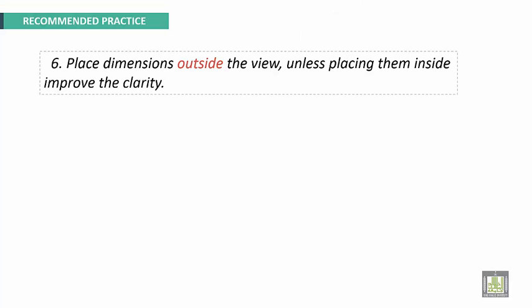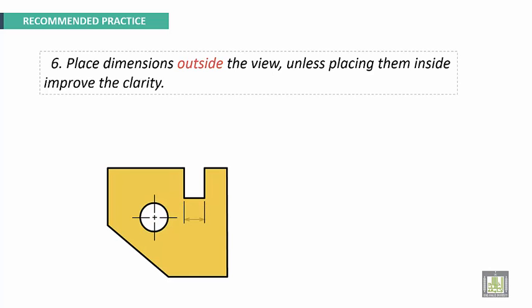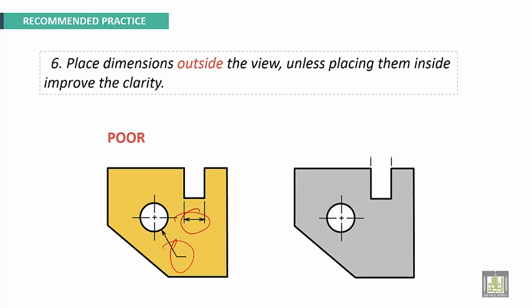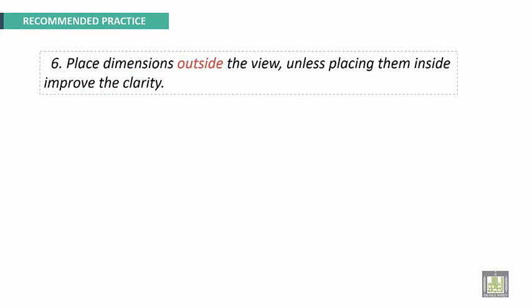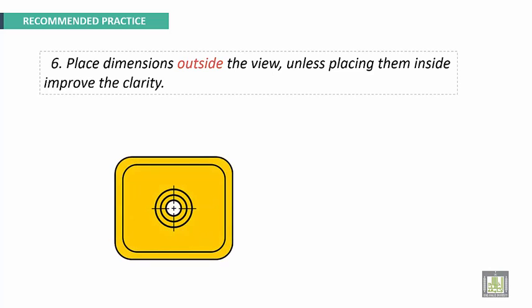Next recommendation: place dimensions outside the view, and placing them inside less often improves clarity. For example, here, there is no need to put it inside. Also this one should be put outside the view. This is good. Place dimensions outside the view; placing them inside less often improves clarity. This is another example here.